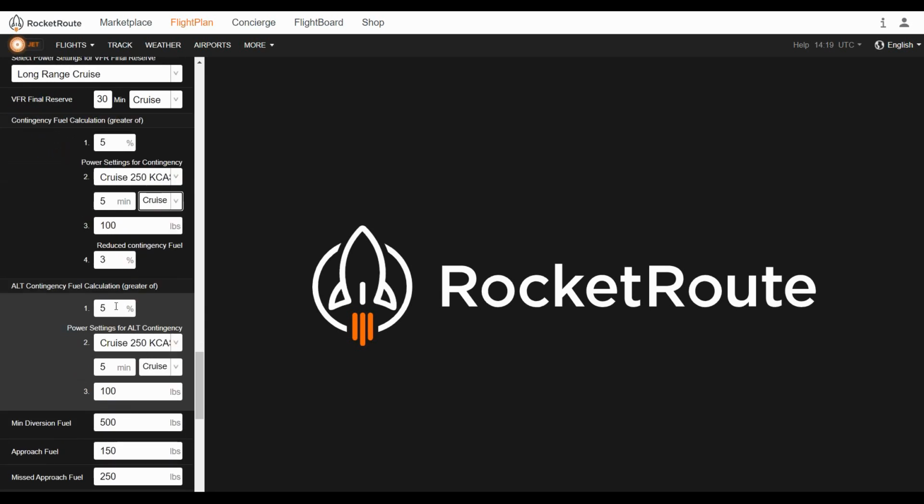Our system will choose the bigger of three: either the 5%, or the 5 minutes at cruise with certain power settings, or a certain amount of fuel. Further, we have the minimum diversion fuel. It can also define approach fuel.